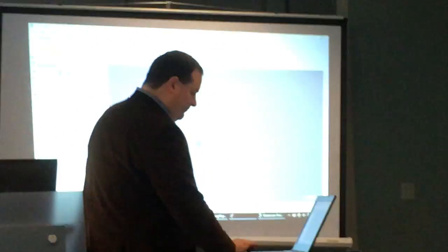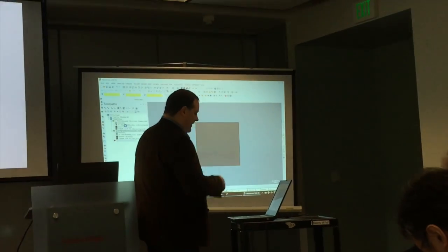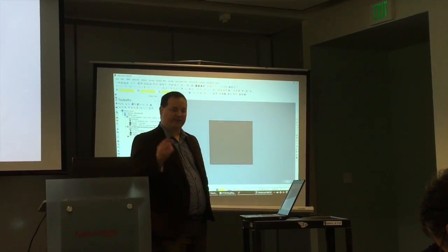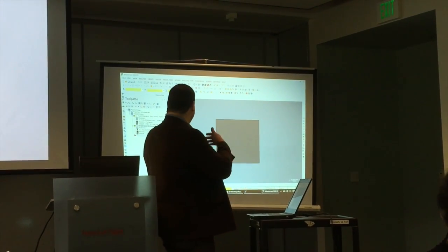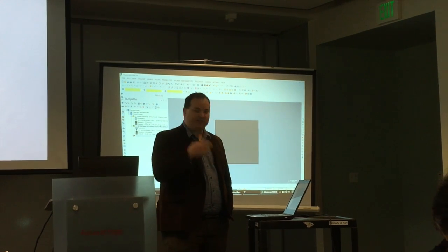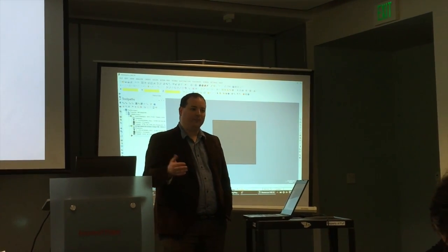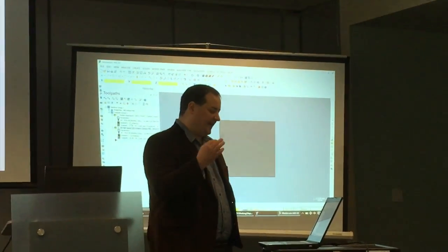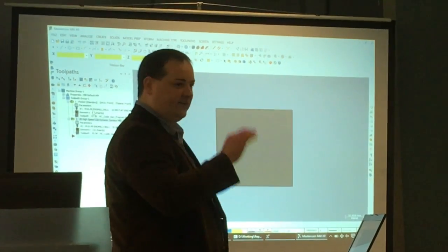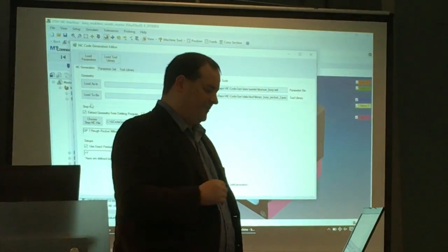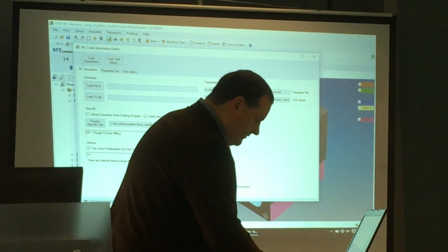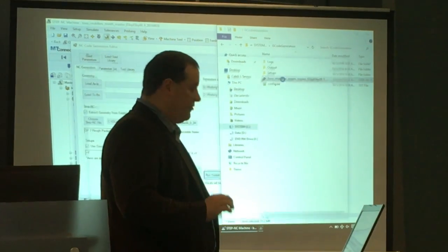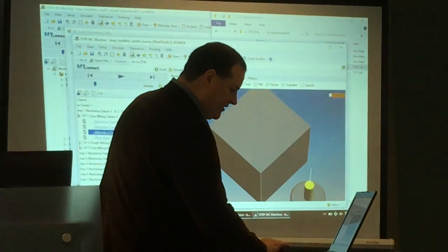Now we launch MasterCam, because once we've identified a feature and looked at the tool settings and decided that in this case we want to generate 2 machining operations, because it so happens that the tool we provided has 2 settings. One is a high material removal rate, but can't handle small radiuses because we have to maintain a very constant chip load. And a second setting that can get into the tight corners, but it doesn't remove material as fast. And so we separate the machining into a bulk removal operation and a corner cleaning and finishing operation.